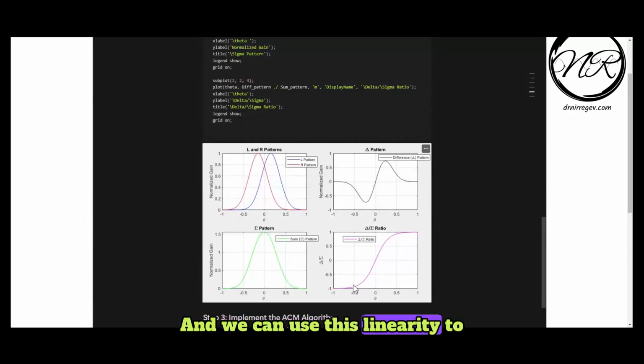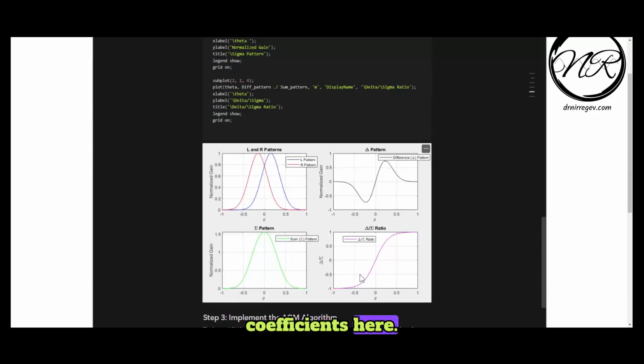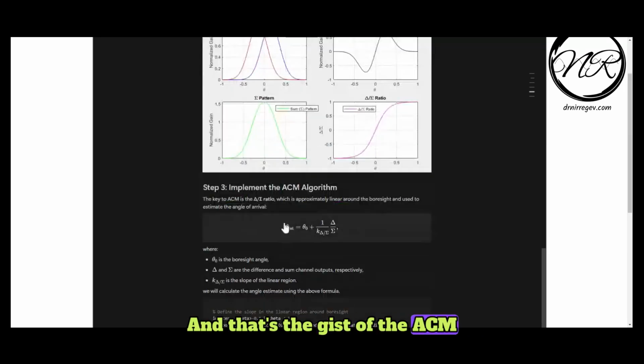use this linearity to calibrate the antennas and the beams such that we have the linearity coefficients here, like the slope, and we can use this slope to predict which angle we are getting the target from. And that's the gist of the ACM algorithm.